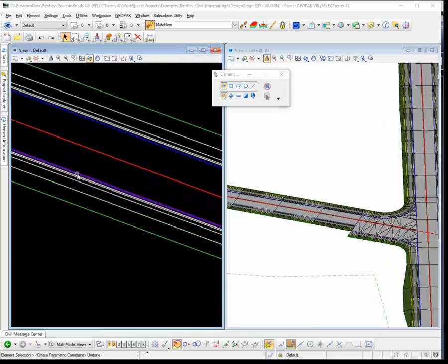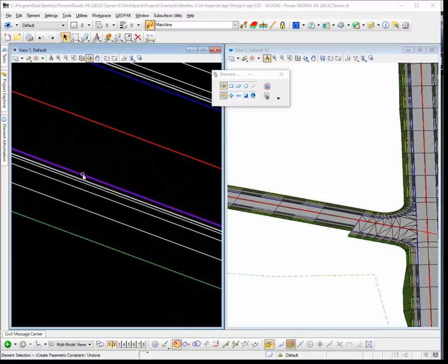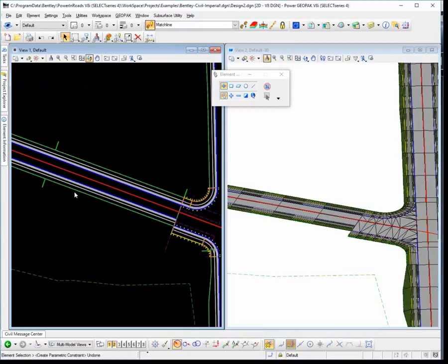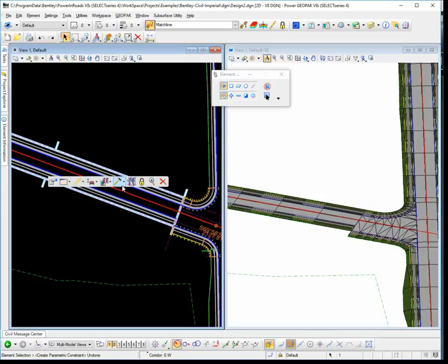We take a look here, our corridor is already drawing our edge of pavement for us. It's essentially a child of the corridor because on the linear feature we turned on the property to automatically create that template geometry in our 2D plan. So I could go out here, for example, and draw a lane line that tapers from 12 feet to 24 feet, or I can just use a parametric constraint instead of targeting point controls.